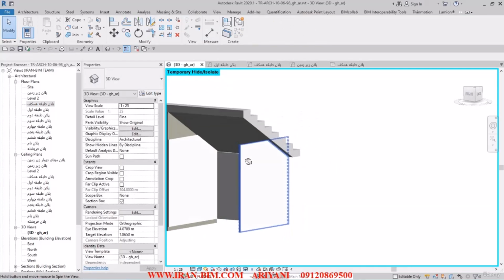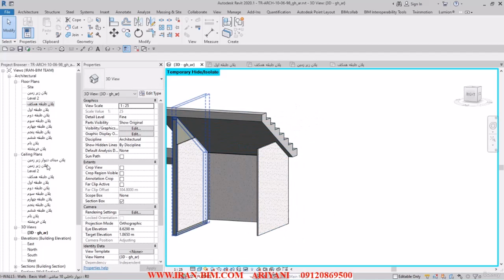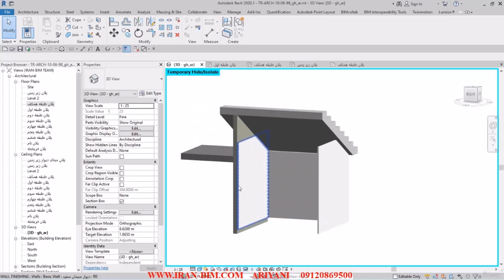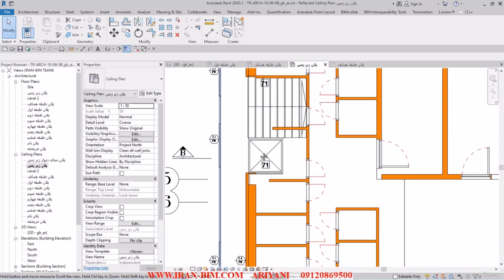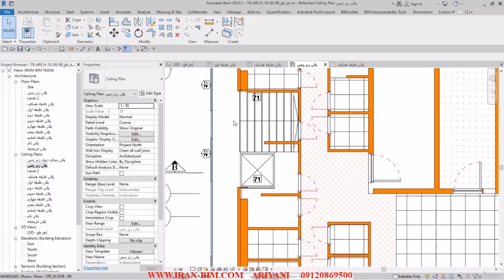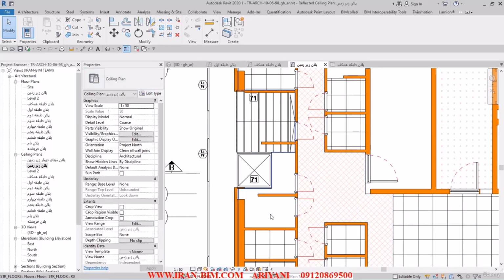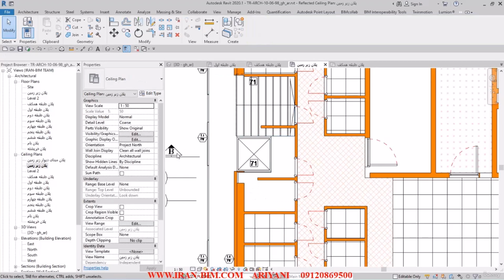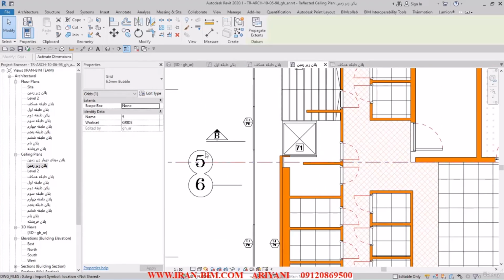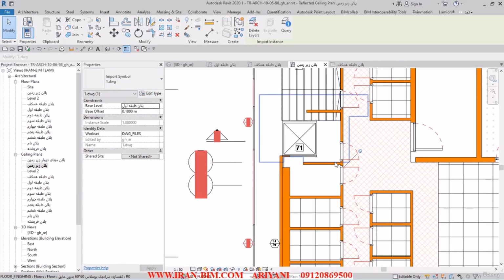So now let me just go back to the ceiling for the underground level, and then I'll just leave this one to be here. Let's go to the plan. So there it is. And here from this plan, I'll select this ceiling over here. So here we do have AutoCAD detailing, which we need to look at. All right, so select the base offset and pull it 2 meters upwards.